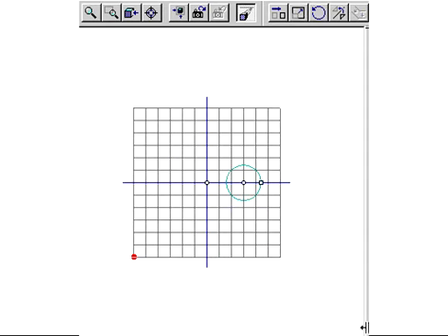To create a mirror image of 2D geometry, select the item or items you want to mirror and choose the Mirror Curves tool. Select the curve or draw a new curve you want to mirror about.